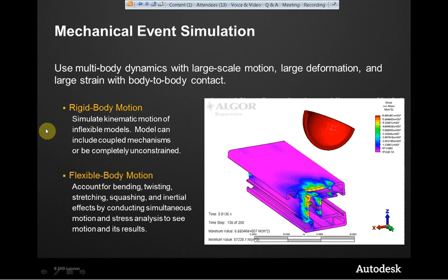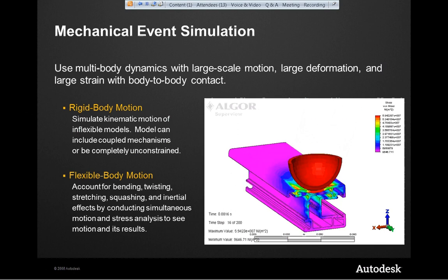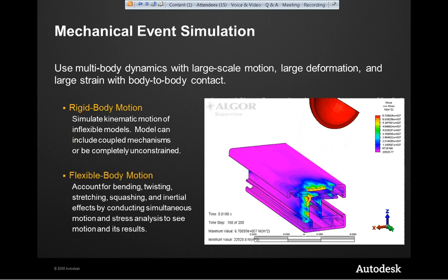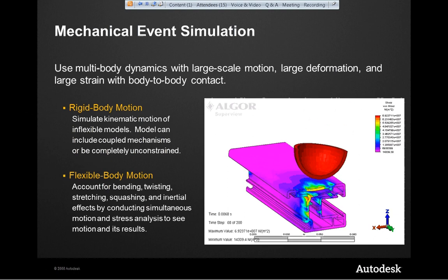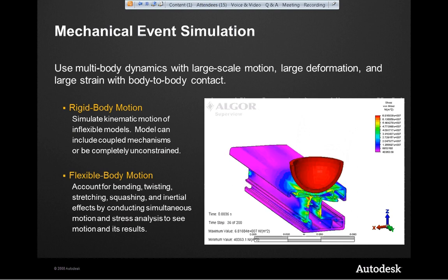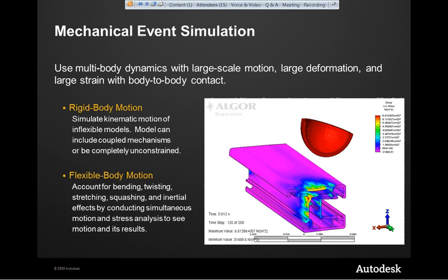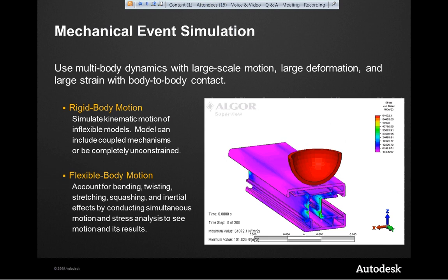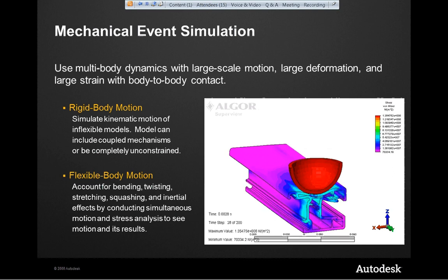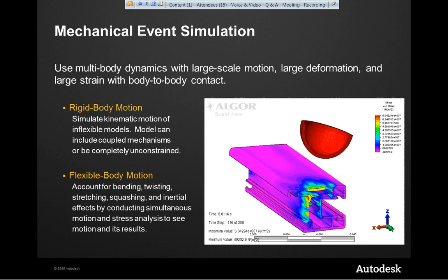You often check a design while it is moving in a dynamic event, such as buckling, swinging, rotation or oscillation. Mechanical event simulation combines kinematic, rigid and flexible body dynamics and nonlinear stress analysis capabilities. As a result, MES can simultaneously analyse mechanical events involving large deformations, nonlinear material properties, kinematic motion and forces caused by that motion, and then predicting stresses.